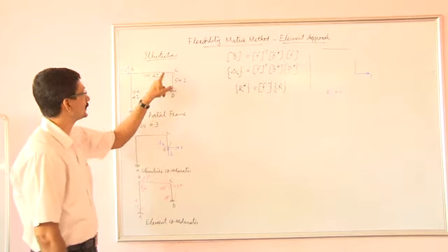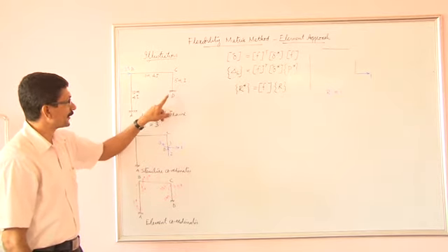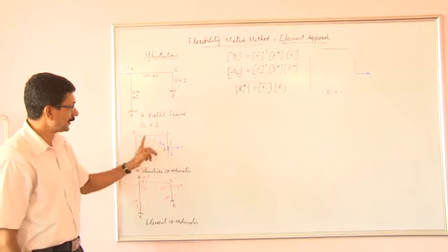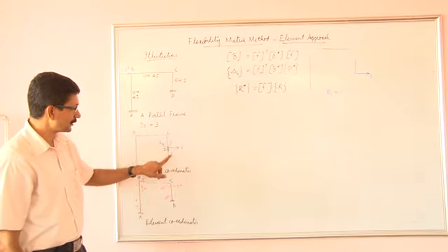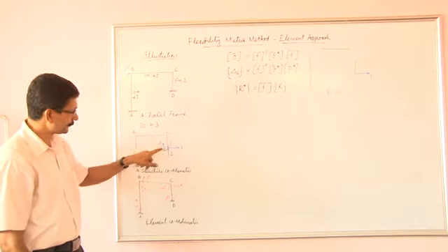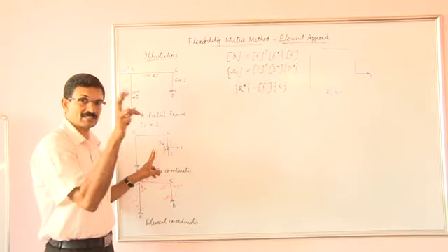The first step will be to find out the degree of static indeterminacy, and that is equal to 3, as is obvious from the previous sessions. Now structure coordinates are assumed by removing support D from the joint, and assuming coordinates: horizontal is the first coordinate, vertical is the second coordinate, and this rotation, or rather the moment over here, would be the third coordinate. These are the structure coordinates as assumed in the previous section also.